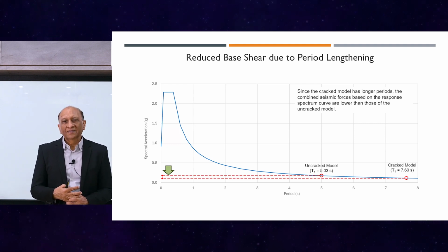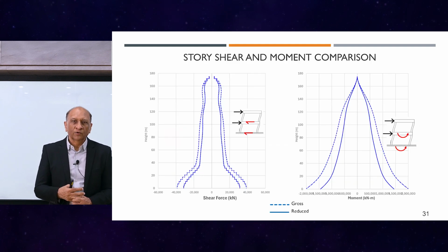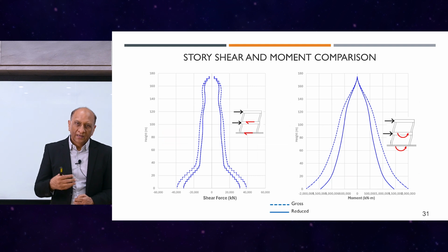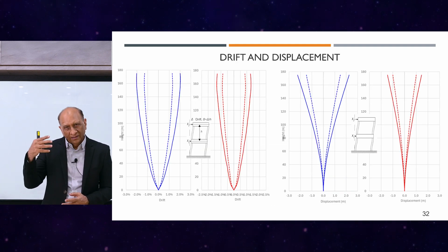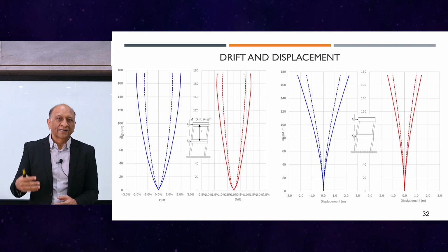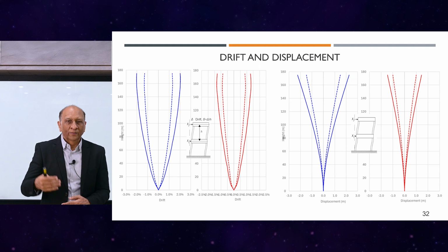So basically, the net reduction we will get at the top of that curve will be 2 times from the elastic force level. Now, typically, the normal members will be designed for the force divided by R, and critical members and critical actions will be designed by the elastic force level divided by R, amplified by omega.